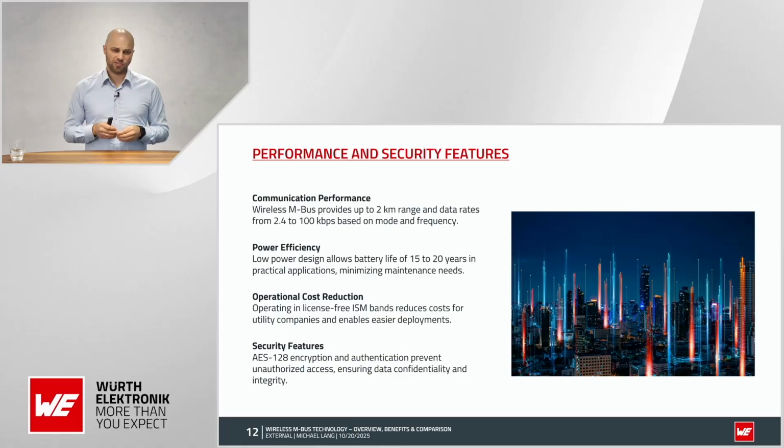Power efficiency is also very important because in some devices you do not have the possibility at all to change the battery. And as you know, metering devices very often have time scales of 8 years, and then they have to be removed. Of course, you don't want to change the battery in this time, and that's very often easily possible with wireless M-Bus.